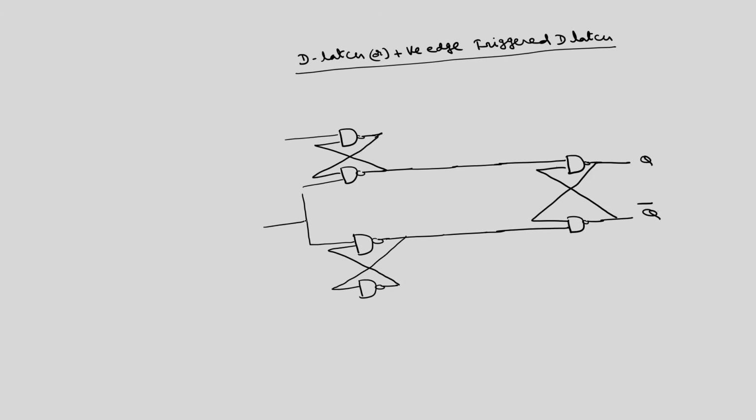Here we are going to apply the clock signal Cp, because this is negative edge triggered. So, we cannot call as enable, we can call as clock signal. So, this is having of course third input also, this is having 2 inputs, the second input of this one is D. So, the D input of D flip flop. Of course, this is connected to this.